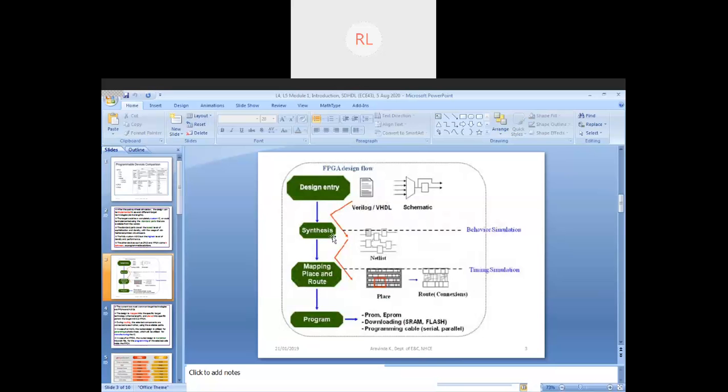So once this is done, next, at the behavioral simulation level, you will try to synthesize them, which means you will try to give some clocking information to them. And once you feel that everything is fine at this particular level, you go ahead with your timing simulation. Now in this timing simulation, what do we try to understand? We try and analyze if data is passing from one end to another in a particular time frame. Is there a delay? So timing is one such important parameter. Now yesterday I was telling you about placement and routing, right?